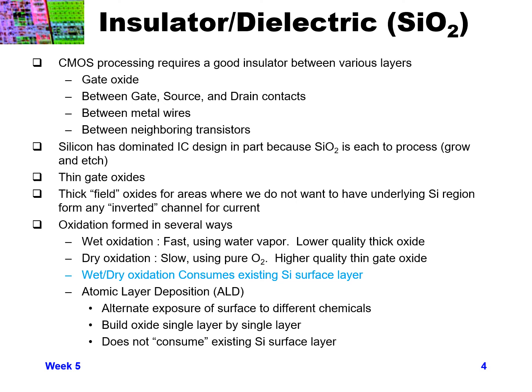Now, in silicon, there are multiple different ways that we can form these oxides. One of the quickest ways is what's called wet oxidation. If we put silicon into a furnace along with water vapor and heat it up, that water vapor will start reacting with the silicon surface and forming silicon dioxide.